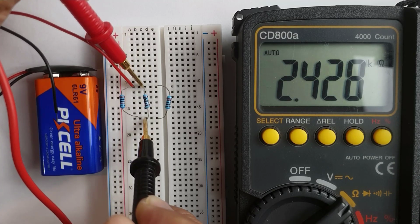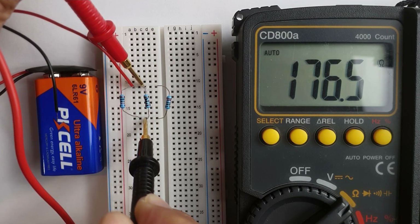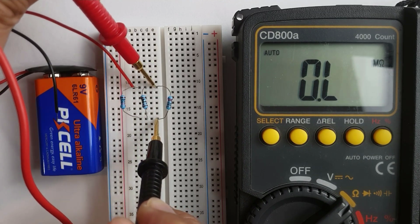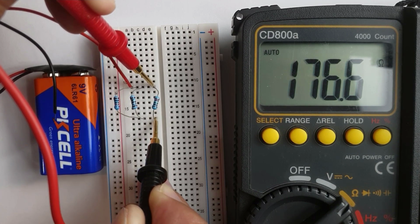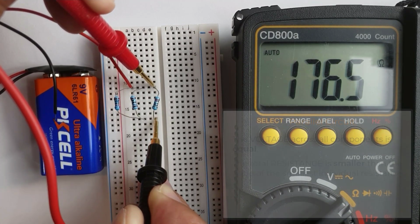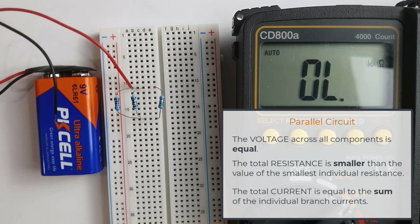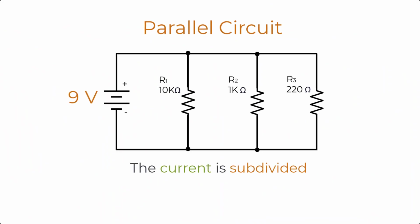Well, it's not exactly the same because the actual values of the three resistors are not exactly 10 kilo ohms, 1 kilo ohm, and 220 ohms. They are off by a few ohms plus or minus. Finally, the third principle states that the total current is equal to the sum of the individual branch currents. It means that in a parallel circuit, the current is being subdivided instead of the voltage. That is why it is commonly referred to as the current divider circuit.